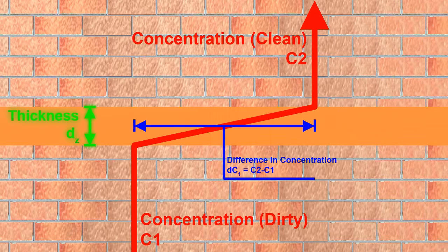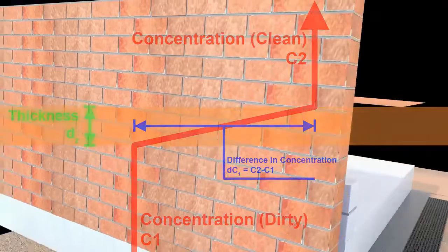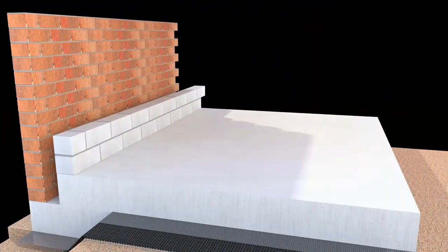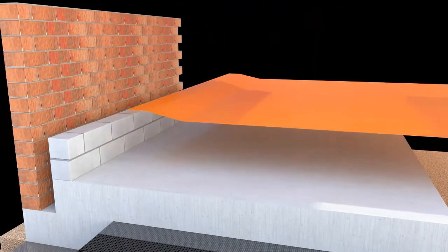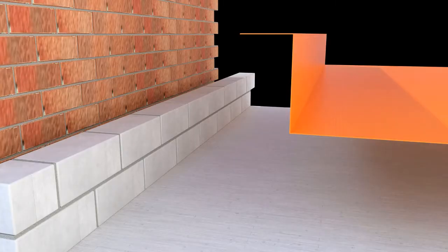What is less well understood is the impact this can have on the detailing due to the flexibility of the membranes. Thick, bulky membranes may perform well when used in large flat areas with a few complex angles, but when used in situations such as raft foundations, they can be susceptible to certain problems. Firstly, when the membrane is folded around tight angles, the molecular structure of the material can open up on the external side of the angle. This will affect a corresponding change in the partitioning characteristics in that area.